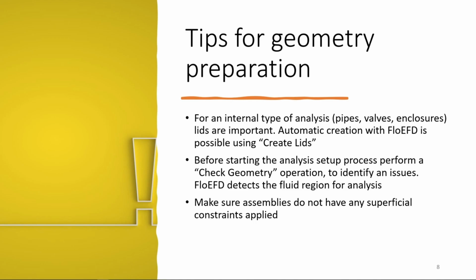Then before you start an analysis, make sure that you perform a check geometry operation. This is really helpful to make sure that all the necessary internal areas are captured where the flow analysis will actually be happening. And if you have assemblies for flow analysis, make sure that you don't have any superficial constraints that are not possible in real life.